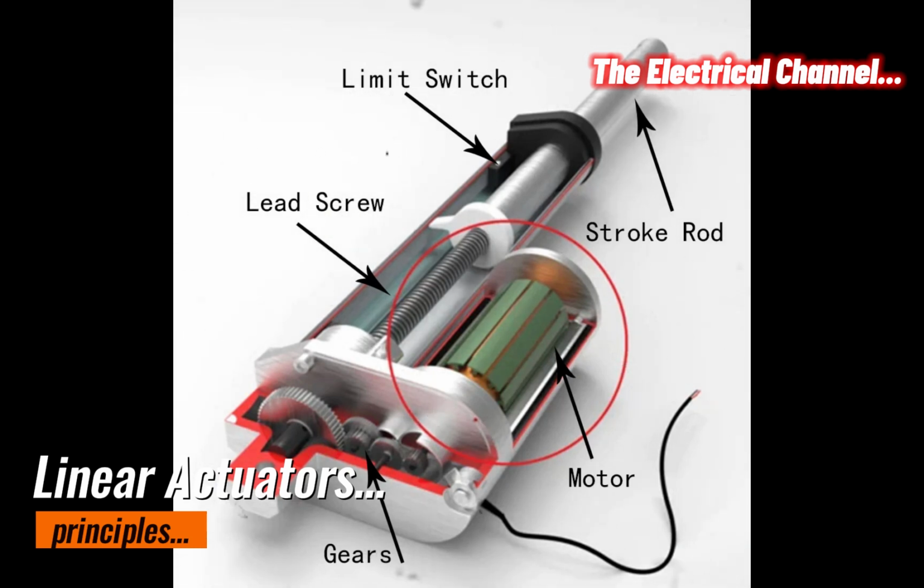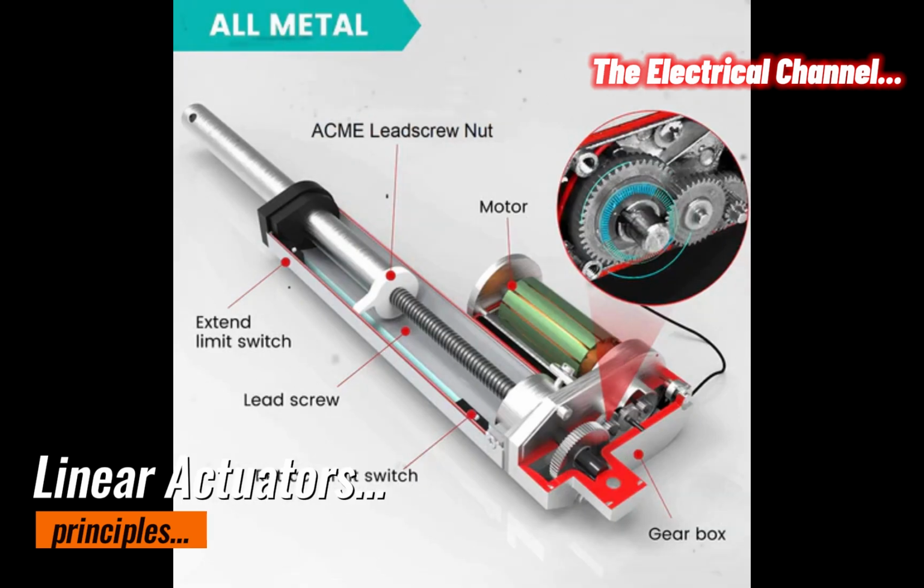In the mid-1900s, the mechanical linear actuator as we know it today began to emerge. The basic design of the mechanical linear actuator takes rotary motion and converts this into linear motion to drive the actuator. There are a few ways in which this can be done. Screw type, such as a ball screw, lead screw, or roller screw.